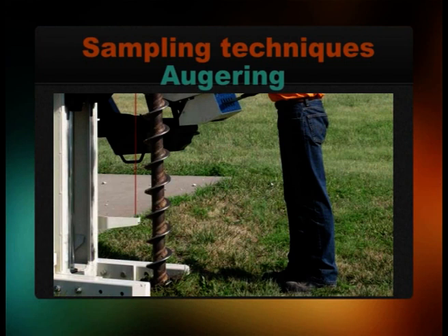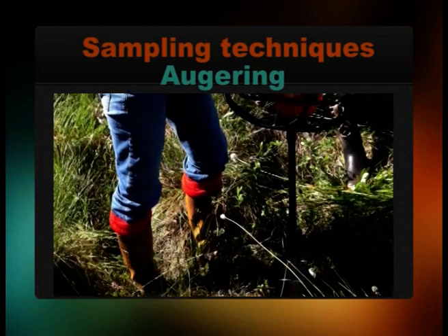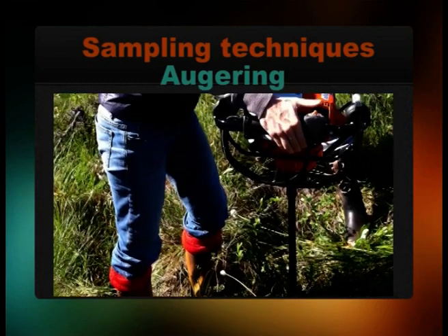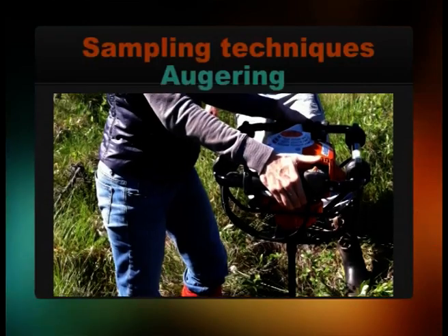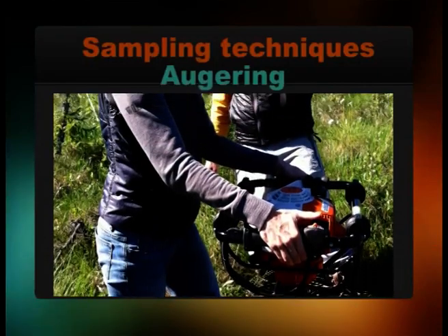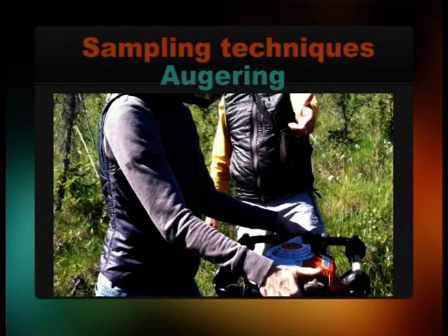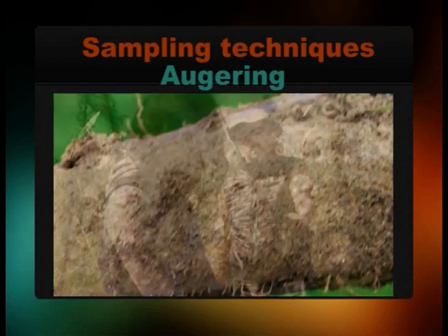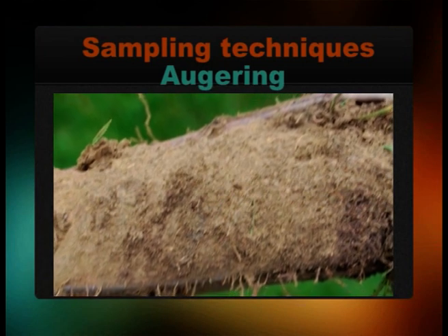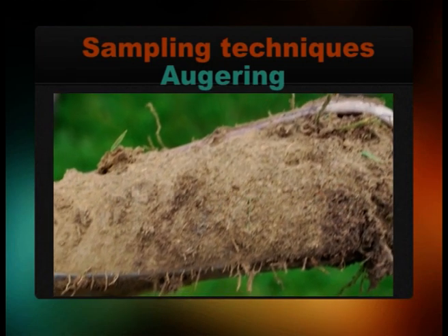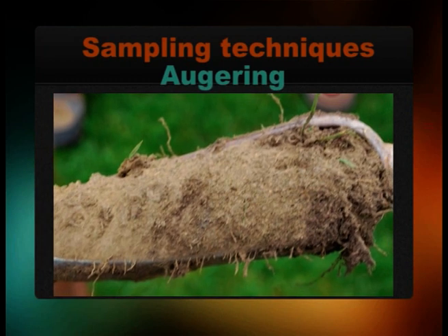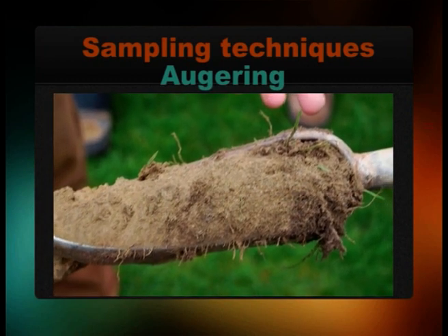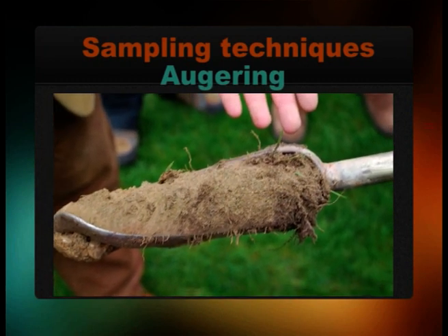One auger hole may answer specific questions such as how deep is this ditch and what type of deposit is at the bottom. But when carried out over an area at regular intervals, an auger survey may give a very useful preview of the types and depths of deposits which may be encountered in subsequent excavation. These observations can be used to create a three-dimensional computer model of subsurface layers.